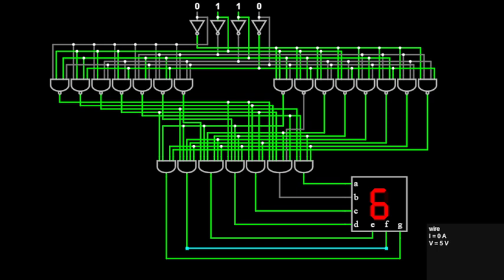That's where the decoders come in. The 7 segment LED decoder takes binary input and converts it into the signals that control each segment of the display. There are various types of decoders, such as BCD to 7 segment decoders or binary to 7 segment decoders. And today we are discussing the binary to 7 segment decoder, each with its own functionality.